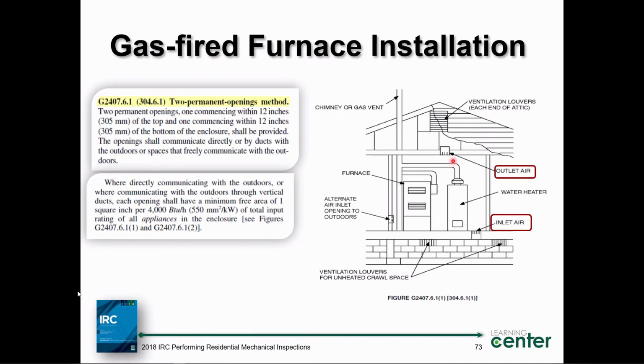You take air from the attic space and you can say that is outside air. Now, how can I take air from an attic space and consider that to be outside air? That's the first question I have. Can you do that? The answer is yes, you can, provided that the attic space is properly ventilated according to the building code. You know that, right?